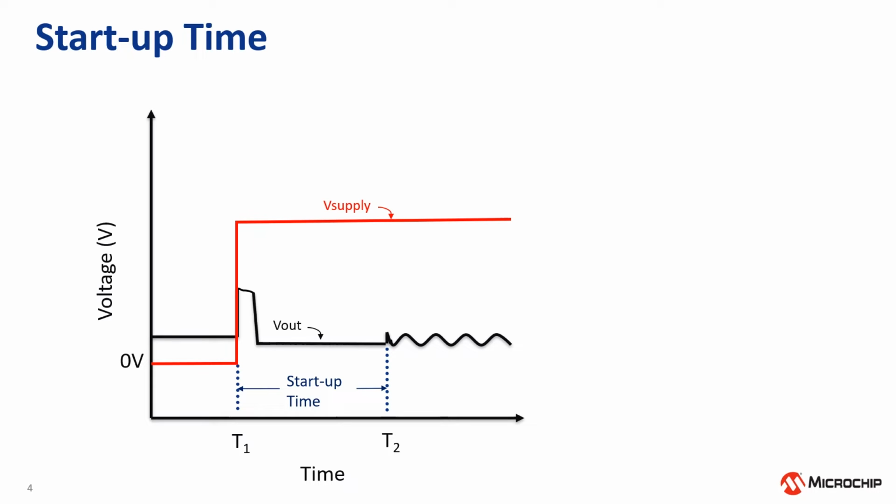Why do we care about startup time? Well, many battery powered applications will put active circuits into sleep mode to conserve battery. For example, some systems would simply disable the V supply on circuit blocks. So the faster a block can reach the steady state, the sooner the system can do its signal conditioning and data logging. Then the system can get back to sleep again to conserve battery.